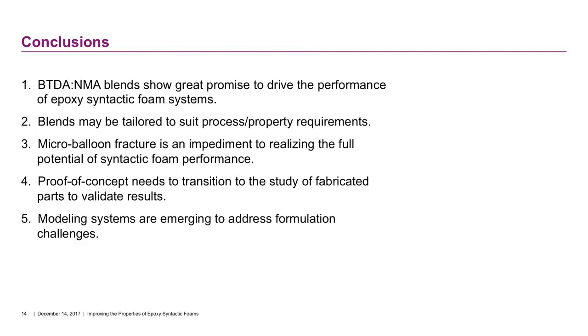I'd like to conclude with the following remarks. First of all, I think we've demonstrated quite clearly that different curative blends, specifically BTDA and NMA, can really show great promise. If you put them together in different ratios, you can impact some of those performance properties quite markedly. So that's worth considering going forward in terms of what the right blend is, and do you need to tailor the blend in order to suit the particular process requirements or property, whatever is more important to you. Now you see the various levers in action and how they work in regard to one another.